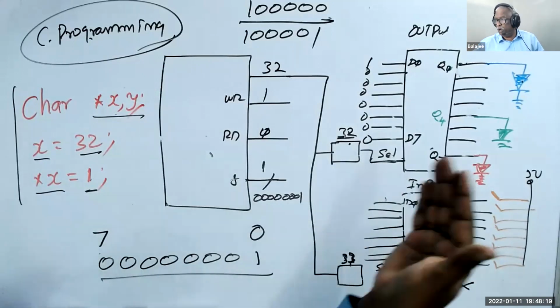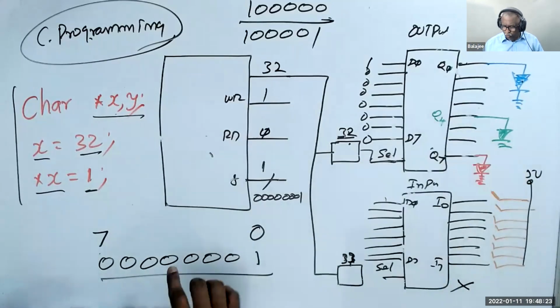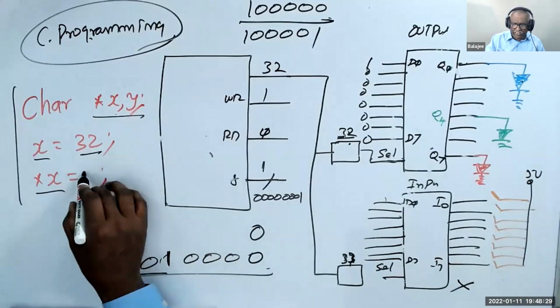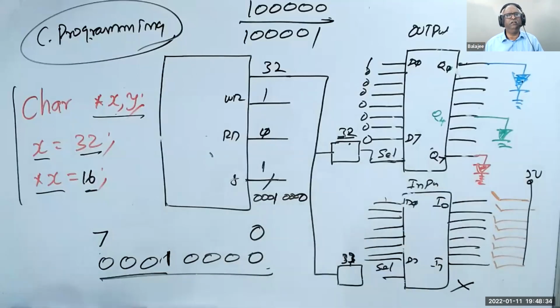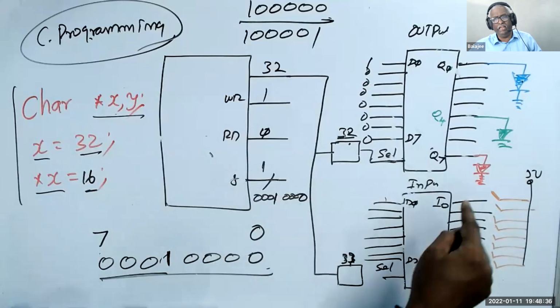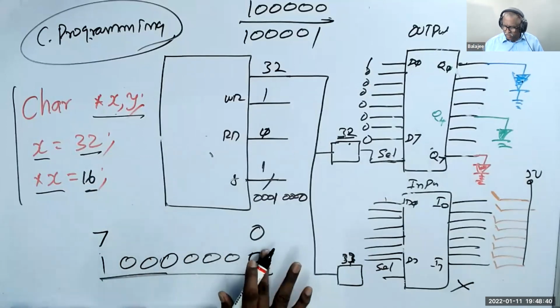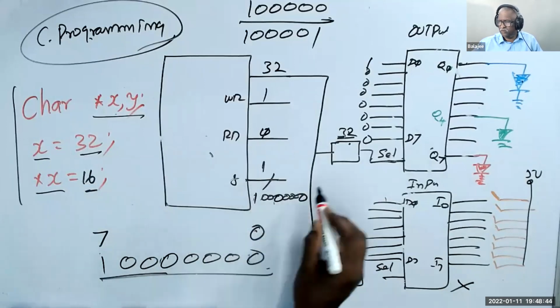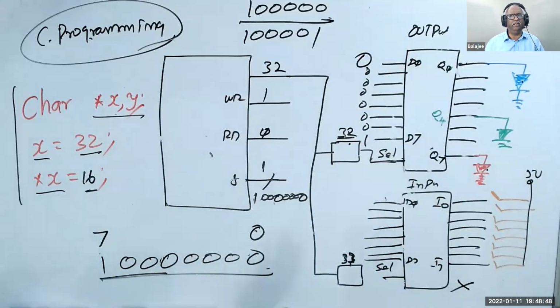This is called output. Now I wanted to on the green LED. That is bit 4. The fourth bit becomes 1. This becomes 0. That means that the value is 16. I put 16 here. That is going to be on green. I want to on the red LED. The last one is 1. All are zeros. That means that 10000000. It is on. I can make that.